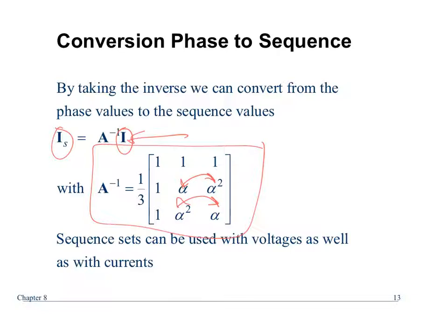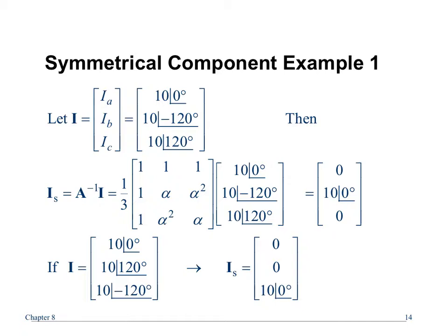So all relays do all day long is they monitor voltages and currents, real-world voltages and currents. Some of them that are doing the residual are calculating 3 times I0, measuring 3 times I0. But all the new stuff doesn't need to do that anymore. Okay? So a lot has changed, but this now is way more important.